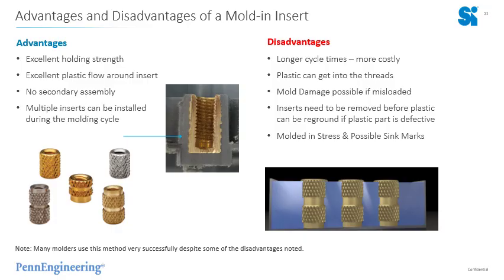If you find that the plastic part is defective, inserts need to be removed before the plastic can be reground, and removing that insert can be quite difficult. Molded in stress and possible sink marks can occur.